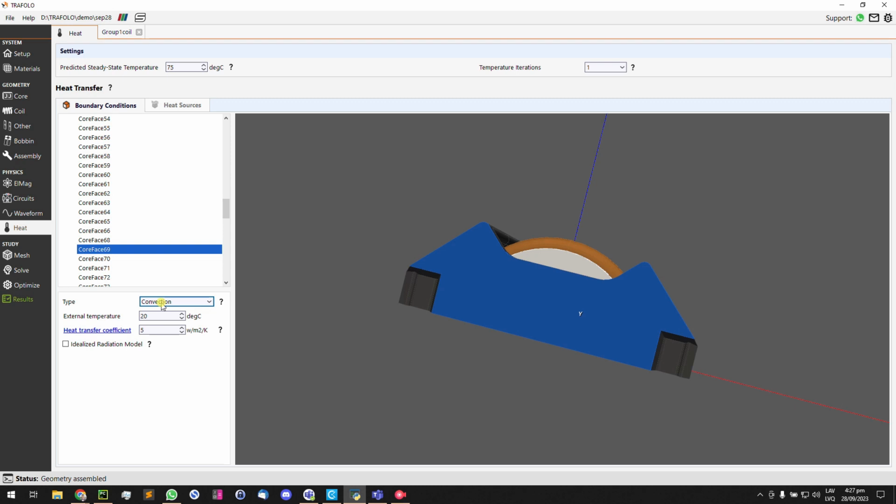If you are talking about, for example, Litz wire, then things are a bit more complicated, because for Litz wire or stranded wires, before the simulation, you have to tell the software what the frequency is, what the conductivity of the material is, what the strand diameter is, and so on, so that the software can use the Dowell equation to calculate R AC, R DC.